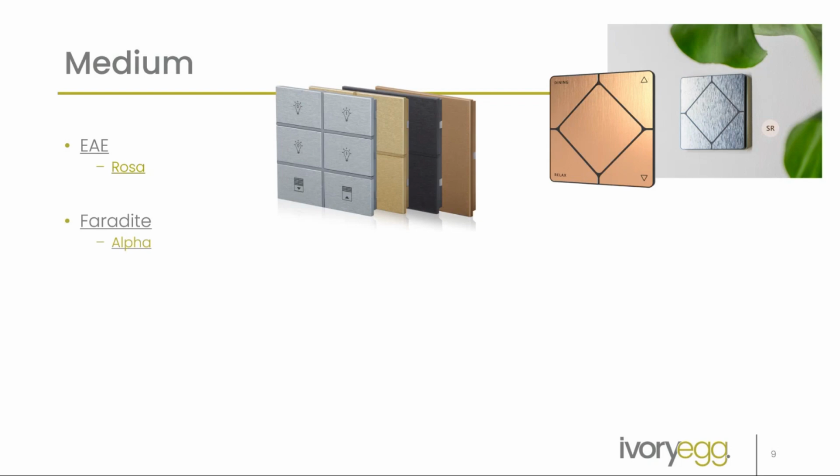The great thing about that is that they use the same bus coupler. They've made a universal KNX bus coupler. You either clip on the plastic cover in the Alpha range, or you go the full hog with the all brass cover. Also good to note with the Faraday is you can have them work with different automation systems. The cover plate is a different product to the coupler, so if you want it to work with a Lutron system, a Control 4 system, or KNX, there are different bus couplers for the different automation system that you want to use.